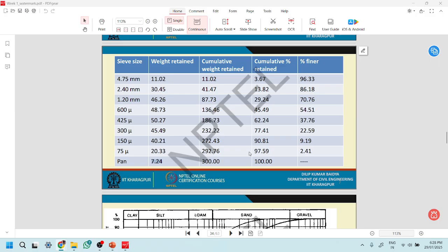For example, fly ash is a pozzolanic substance. There are studies of soil stabilization in which fly ash and other substances that have calcium contents result in geopolymerization, isn't it?